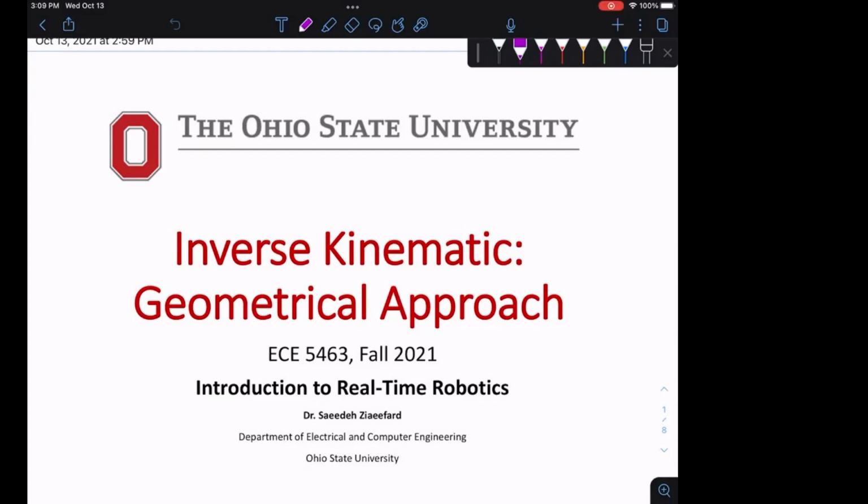Since the robot is moving this way, the solution that is smooth and close to the previous solution is accepted. You don't want to go very quick here and then come back here and come back there. Does that make sense? So you will choose the solution based on what the application is. You'll have multiple solutions, and you have to choose one. When you code, you can always compare with the previous solution and choose the one that's closest, setting a threshold, because both of those are correct.